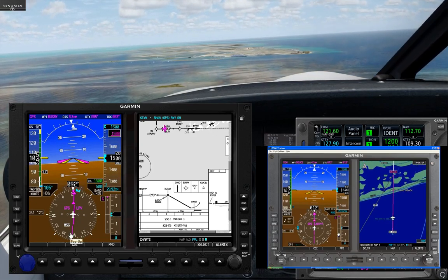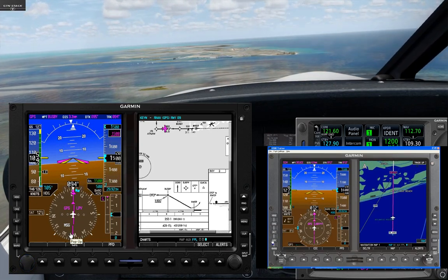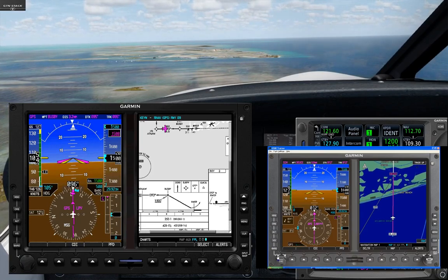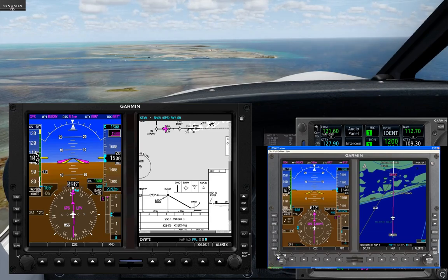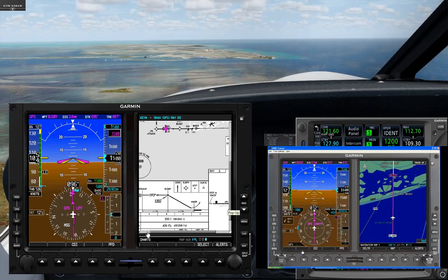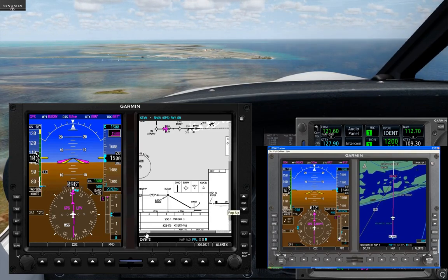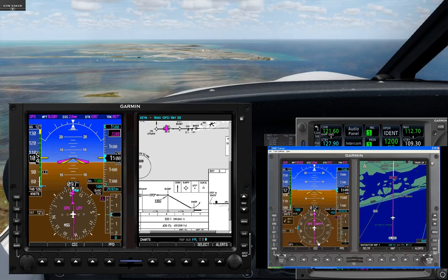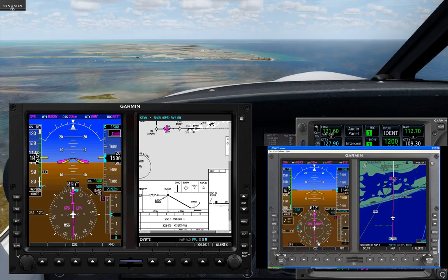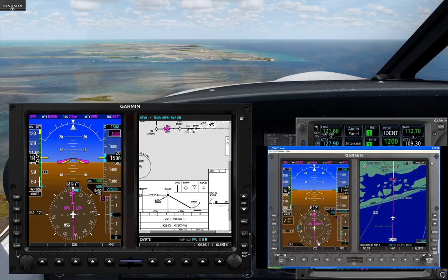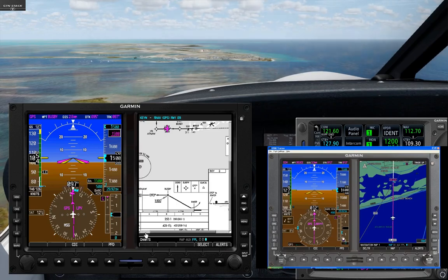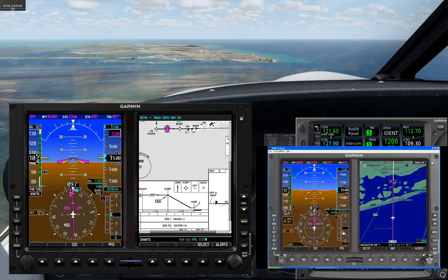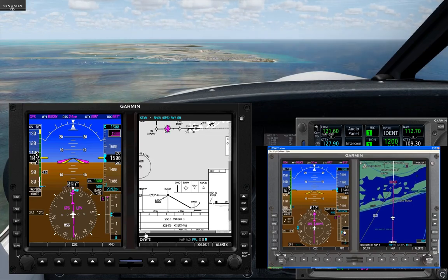I could pre-select if I've calculated my VDP. I could prepare to calculate my vertical speed, and I know that for my non-precision approach I want, we'll say, a 600 to 800 foot per minute descent rate. So I could pre-bug that there so that I know in order to reach the runway with visual reference in sight in the appropriate amount of time, if I can give myself that descent rate, I will be able to see with enough time to make a normal approach to landing.